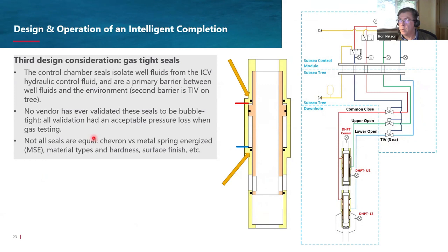Unfortunately, no vendor, and I'm not throwing rocks at any one vendor, they're all in the same boat, has ever tested these seals to be bubble tight. Whenever they've done any gas testing, there have been acceptable loss rates when testing. And if you're operating a well like this, there is no acceptable loss rate. It has to be bubble tight.